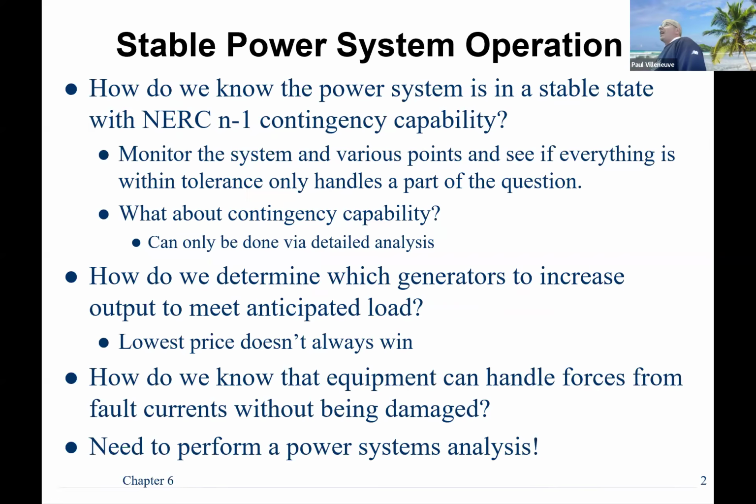So one of the questions is why bother doing this? Well, there's a tremendous amount of effort that is done on a daily basis to make sure that the power system is stable. And what is a stable power system? Obviously, we know that voltages are within tolerance, frequencies are in tolerance, but then we also have this thing called NERC, N-1 contingency, and NERC sort of has been given authority by FERC to set the rules for providing power and how the utility or the power system is operated, at least in most of North America.